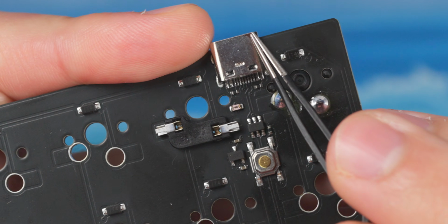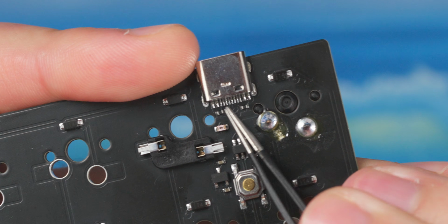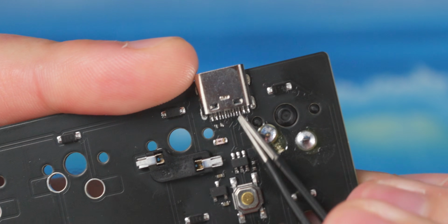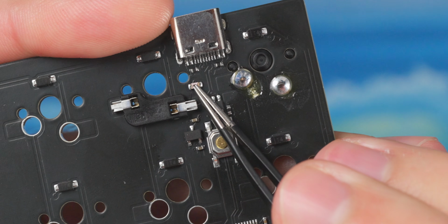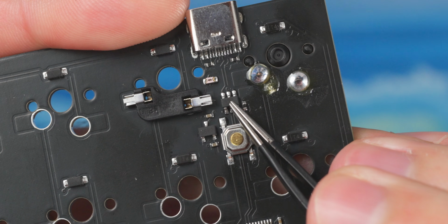What I'd like to do now is take a look at the physical PCB to give you an idea of what this looks like on a real board. If we look up top, we have, of course, our USB-C port. We have our little 5.1K resistors here, which are for the USB specs, so remember CC1 and CC2. We have our resettable fuse right here. That's what the fuse looks like. We have our ESD protection chip down below.